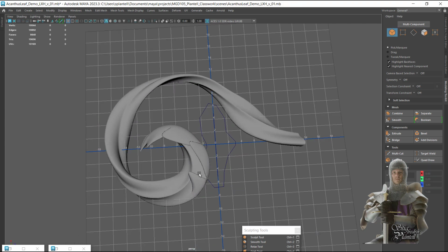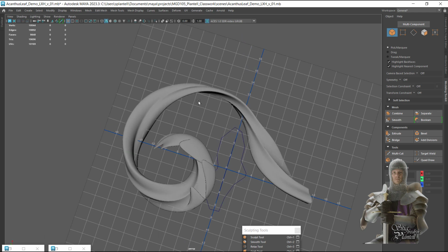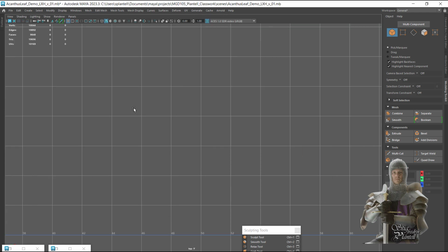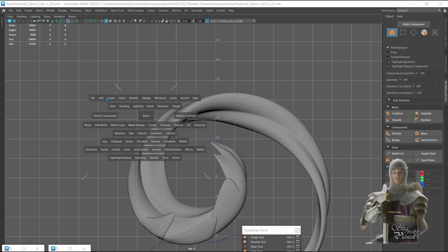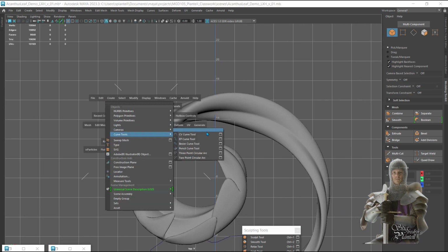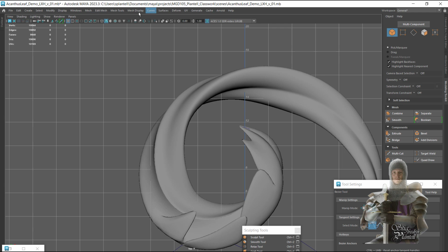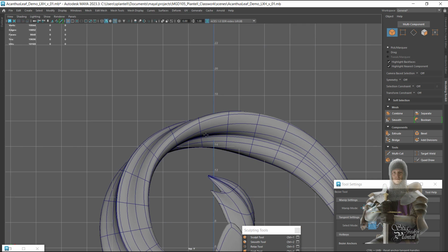I hope that you can understand. You could do more of this all over. I'll show you one more technique. You could do another branching form by coming in here and going, create a new curve. I will use the most simple curve, because I could use a Bezier curve. I think that's fine. Let's go to wireframe on shaded so I can at least see where something might break away.